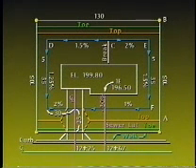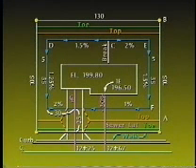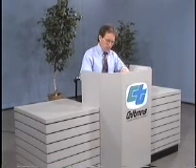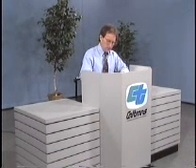From the site plan, the distance from the top of slope to the property line is 20 feet, so the dimension from the property line to the toe is 20 minus 2 times the change in elevation between the top and the toe. As you can see, a lot of time and effort can be saved by proper planning and organization. The method you use is very important.